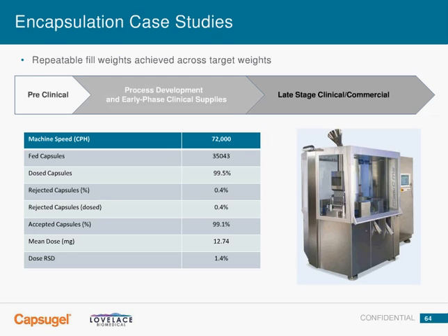Similarly, taking this to the larger scale encapsulator. What's shown here is again almost that same placebo, run during a site acceptance test with the machine at full speed. Basically we just ran it until we ran out of powder, but ended up with a mean dose with the volumetric fill of about 12.5 mg still, and a really low dose relative standard deviation. So I thought that was pretty impressive, again, for a powder that definitely handles pretty poorly compared to some of the other powders we can produce, and in an initial challenge for this machine.